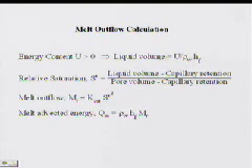So we first calculate the volume of liquid water in the snow. We calculate the relative saturation, which is the liquid volume minus an amount that's just held in capillary retention, that's a parameter, relative to the pore volume. So this is a number that's going to be quite a lot less than 1, because the snow's pore space never gets filled completely with water.